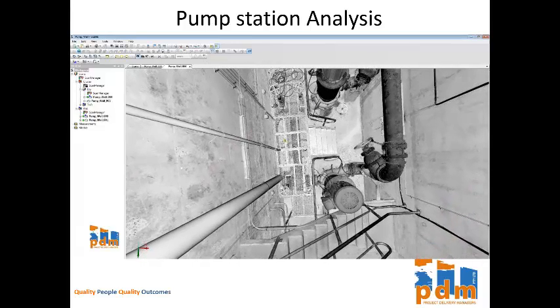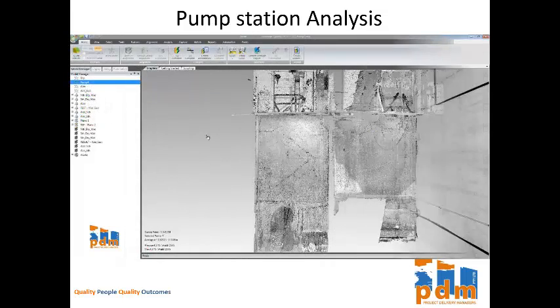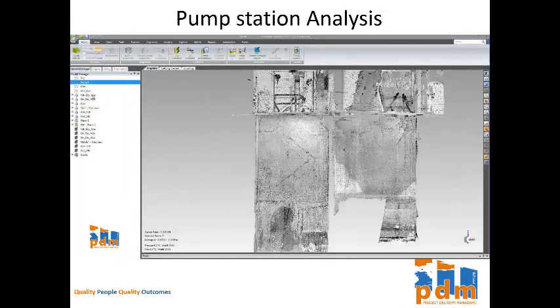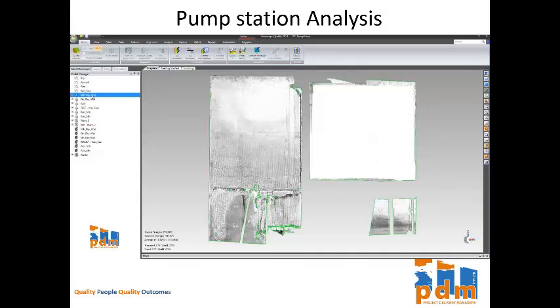From these images too, in the software that we have, we're able to take measurements. The measurement from wall to wall here is 3.51 metres. So what we decided to look at was the alignment, to see if there were any deviations from the dry well, which would be believed to have no issues, taking that line out and putting it across onto the wet well. This is the northern faces, two faces of the wet and dry.